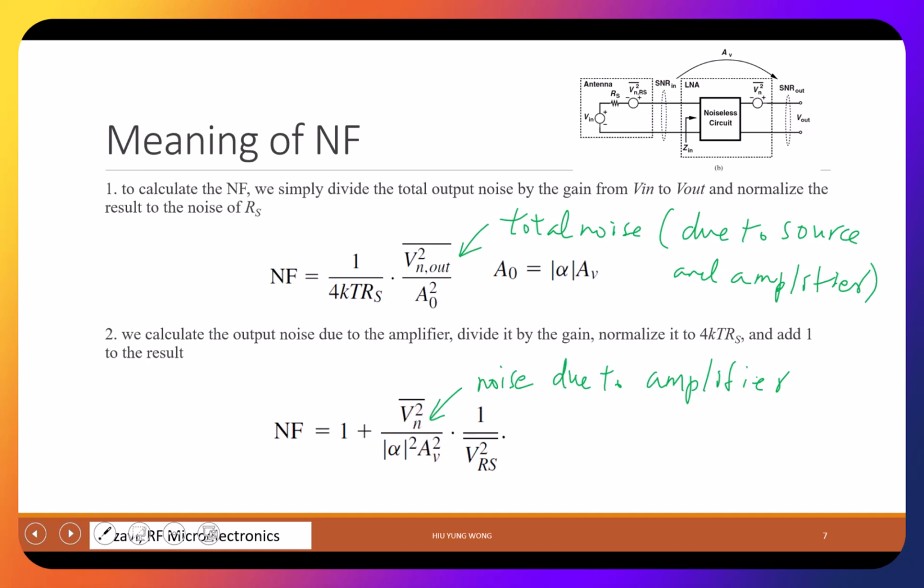And that's why in quantum computing, your first stage is to have a low gain, but also low noise. So you don't want to create a very large amplification, but at the same time, you have a lot of noise. So that's why you use quantum limited amplifier. The gain is not good enough, but you add the minimum amount of noise that you need to add. Then you have another stage to further do the amplification.